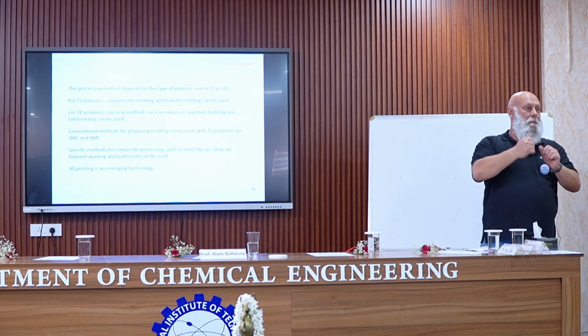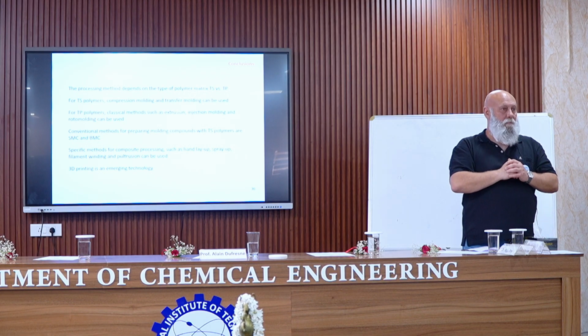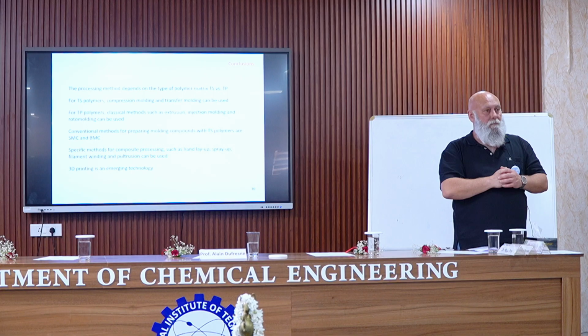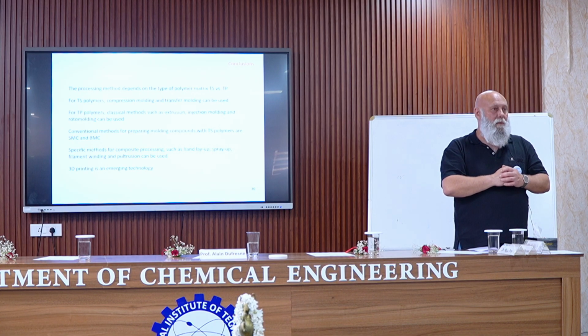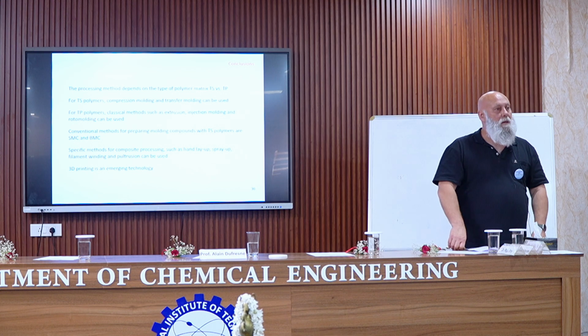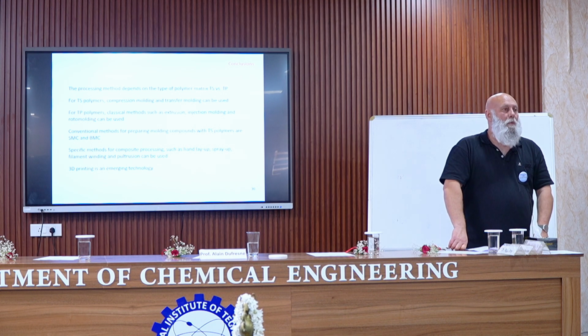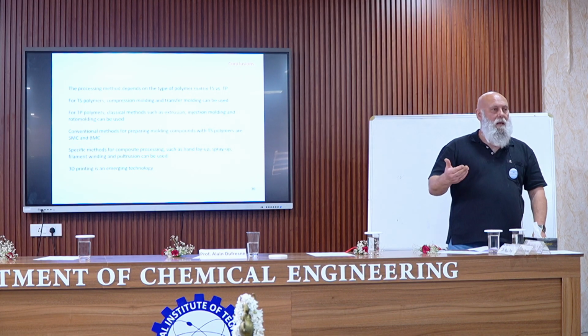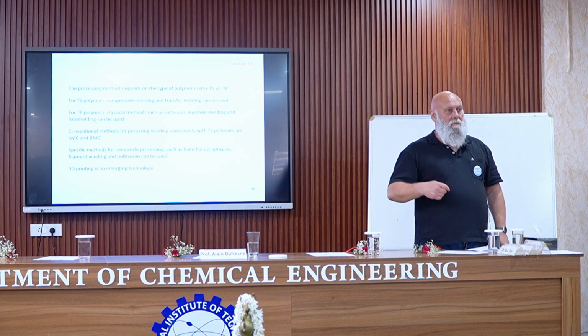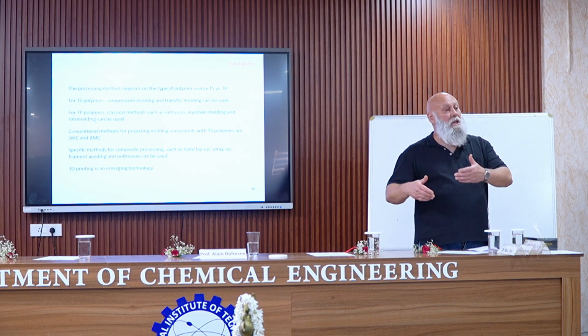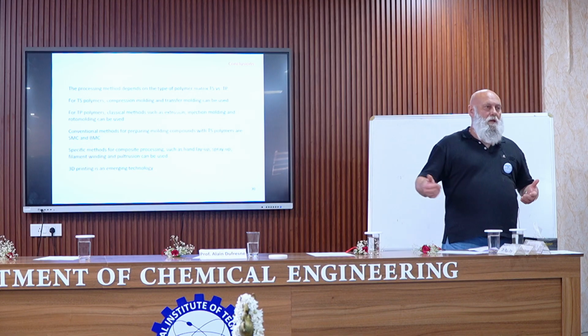Probably in the wood composite the thermoplastic content will be very high, right? Generally polyethylene? Usually it's polyethylene, yes, but it can be polypropylene or PVC also. The problem with PVC, I think, is most probably the thermal stability, because it can be easily degraded. So one of the drawbacks is the change in the color, which in this case is not really important because the material is brown. So you cannot see the difference in the color of the matrix.